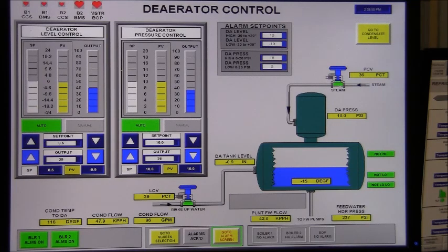Many of these control valves, if they go to 0% output, we will turn the body of the valve red, and that's just to grab the operator's attention in case he looks past the display. Some of them will also flash, but not all of them. Again, it's an attention-getting mechanism just to catch the operator's eye. If this steam valve was closed, the operator might see it and wonder why, look at his pressure and wonder what's going on. Somebody shut off a valve, or is something else wrong?